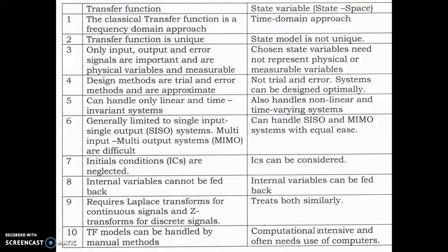Now we will discuss the comparison between the state variable approach and the transfer function approach. Transfer function approach is a frequency domain approach, and the state space or state variable method is a time domain approach. Transfer function is unique, but the state model is not unique.